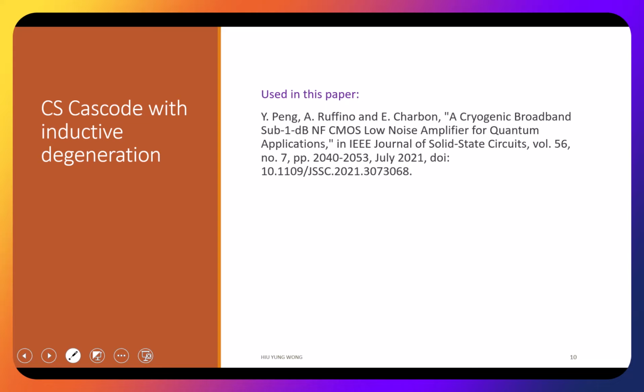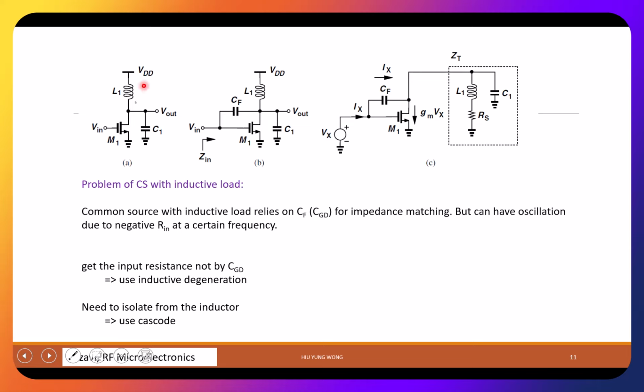This is a common source amplifier we learned at the beginning. And we say we use the inductive loading, right? What is the advantage of inductive loading? Very good. So this has a large headroom, right? Because your drain can go to VDD, and that is what you're doing in your project, right? The drain is very close to VDD. If it is not, your M2 is going to be in linear mode more easily.